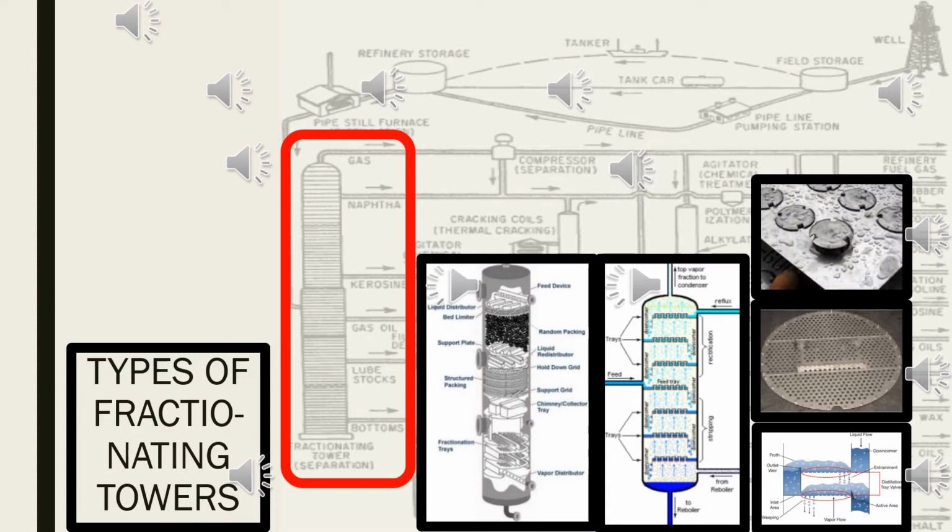You could also consider valve trays. Here perforations are covered by liftable caps. Vapor flow lifts a given cap, thus self-creating a flow area for the passage of vapor. The lifting cap directs the vapor to flow horizontally into the liquid, thus providing better mixing than is possible in sieve trays.